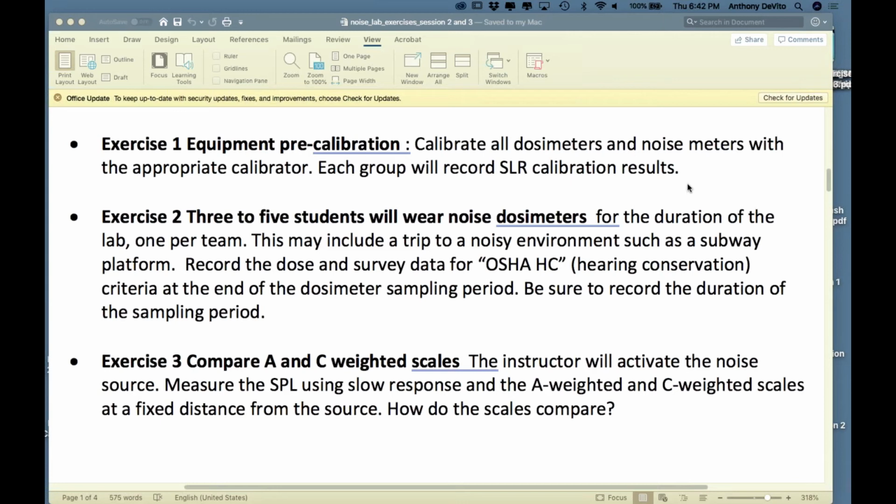You might consider leaving this on the worker for the entire 8 hours. If a worker works 8.5 hours with a half-hour work break, then you might consider, I want to measure 8 hours for his 8-hour exposure. In that case, you would probably take morning readings, pause it, and then take readings in the afternoon. And you should really calibrate anytime you start and stop on this stuff. Okay, sound level meters, you want to calibrate. Matter of fact, let's do that exercise right now. And Michael demonstrated. We have a sound calibration device.